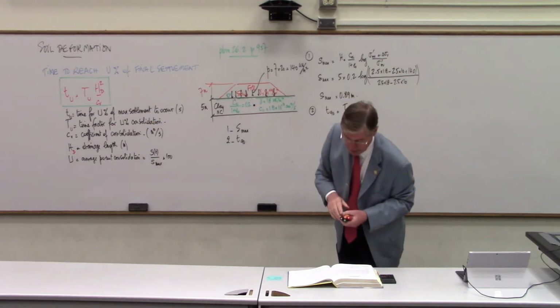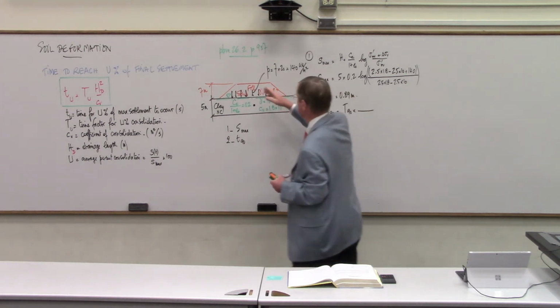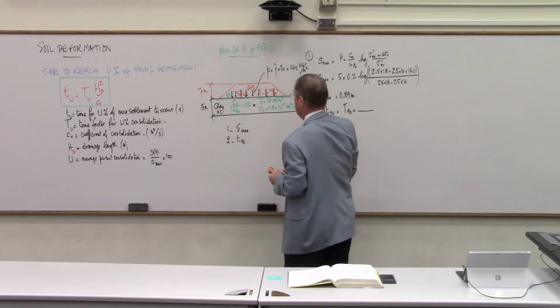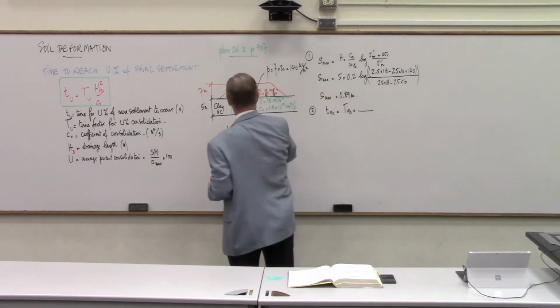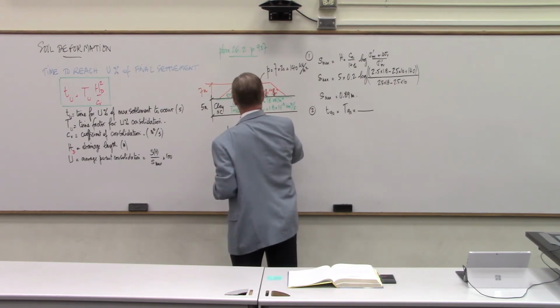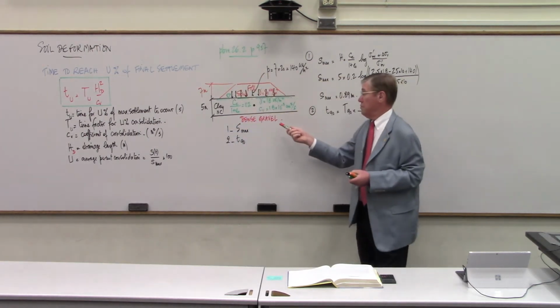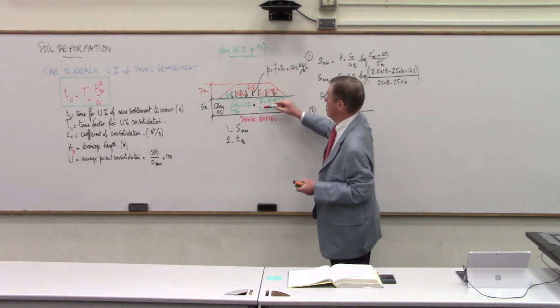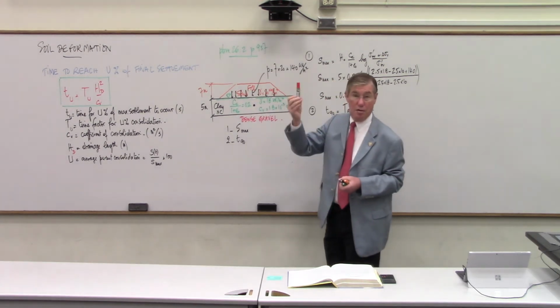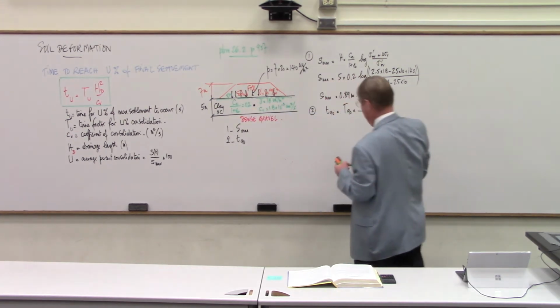Well, I didn't tell you, but in the problem it says that we have the fill above the clay, and below the clay we have a layer of dense gravel. So right here it is dense gravel. Okay? So because it's dense gravel, the water can actually drain through the bottom of the clay layer, and it can drain up into the fill. Therefore, the drainage length is 1/2 of 5 meters.